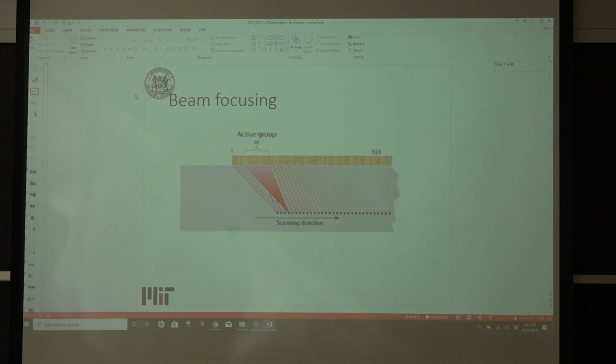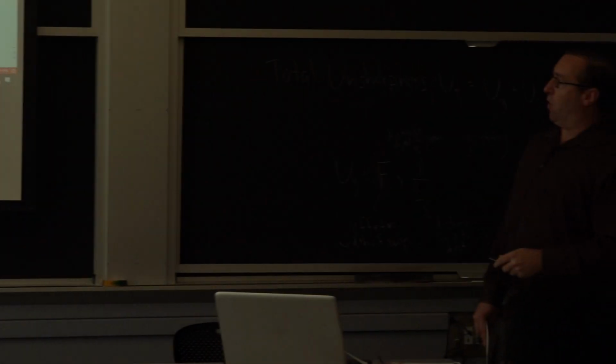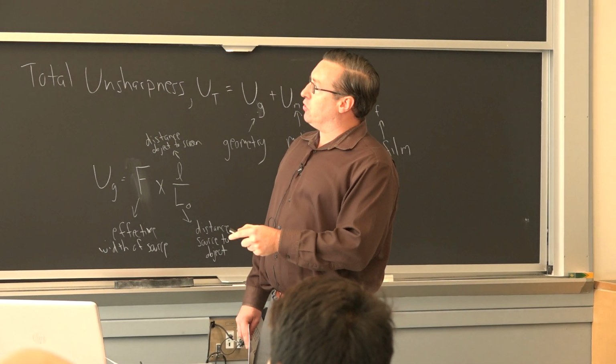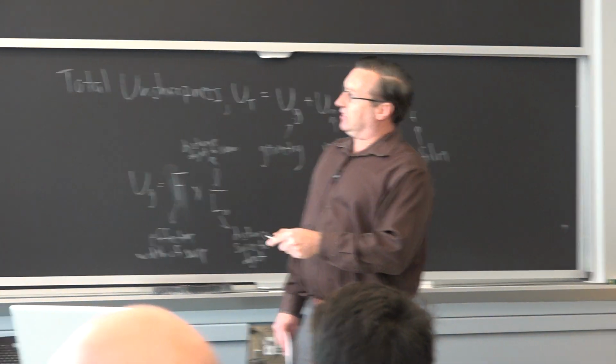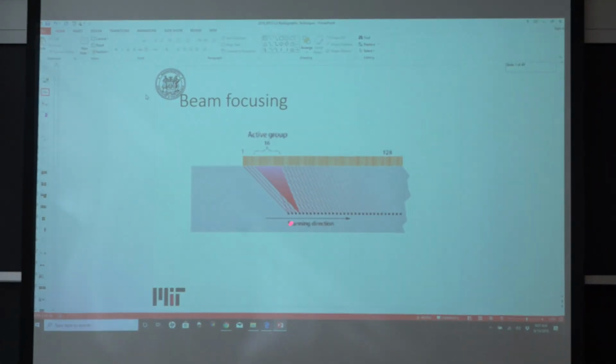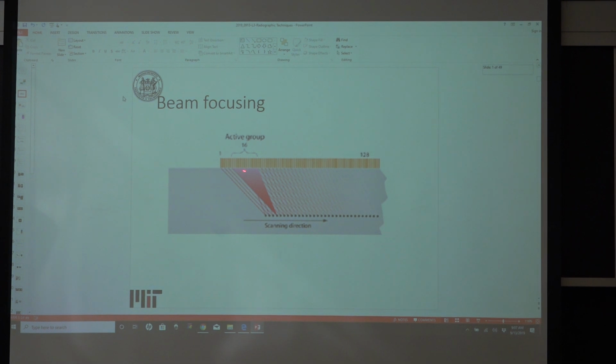We had discussed phased array, how rather than a single element transducer, you can have many transducers, and you can steer the beam by time lapse on when the various transducers send their wave. If this was a longitudinal wave with a transducer pointing down on the sample, this is where you can get your sectorial scans that were shown in the sample yesterday.